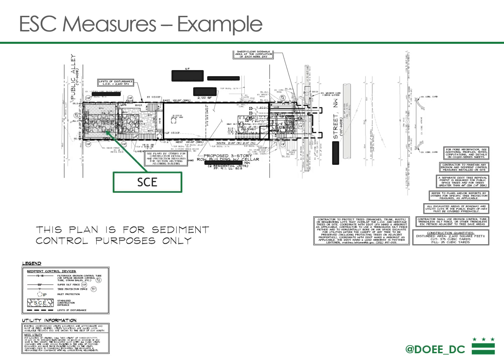Here's an example of a stabilized construction entrance. On these smaller projects, oftentimes it's very difficult to get a 30-foot long or a 50-foot long stabilized construction entrance. The minimum is a 30-foot long, unless it's a large site, then it's a 50-foot long stabilized construction entrance.